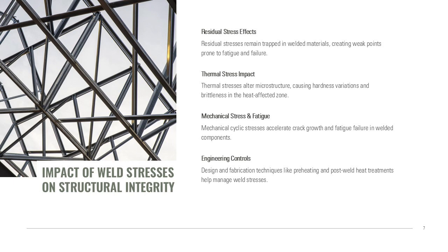Residual stresses often remain locked within the material, creating weak points susceptible to fatigue. Thermal stresses can alter microstructure, leading to hardness variations and brittleness in the heat-affected zone, HAZ. Mechanical stresses, especially cyclic loads, accelerate crack growth and fatigue failure. Engineers must account for these stresses during design and fabrication by selecting appropriate welding techniques, preheating, and post-weld heat treatments. Failure to manage these stresses can result in catastrophic failures in critical structures such as bridges and pressure vessels.